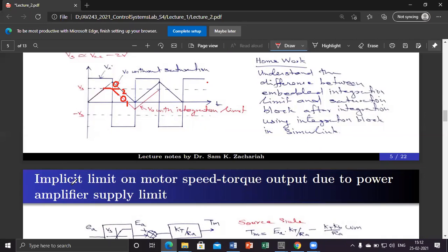You can give an integrator limit in two different ways. One is as it behaves in the real hardware, as case one. Another is a simpler logic. First you simply integrate, get the output of the algorithm, and pass it through a limit. That limit logic is simple.